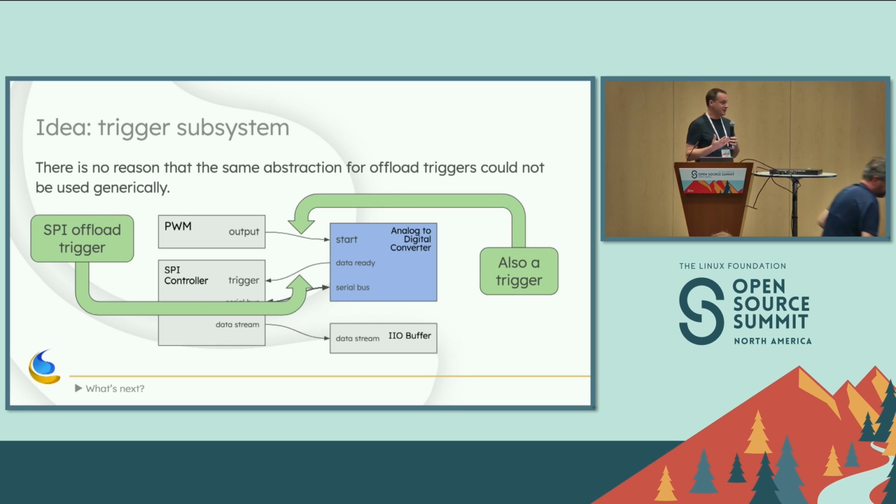So it'd be nice to use those same APIs to just get a generic trigger. Right now we're using the PWM's bindings for the ADC, but there's really no reason it has to be a PWM. It could be a clock or it could be anything else, chained from another ADC. So it'd be nice to be able to just use that more generic trigger binding.